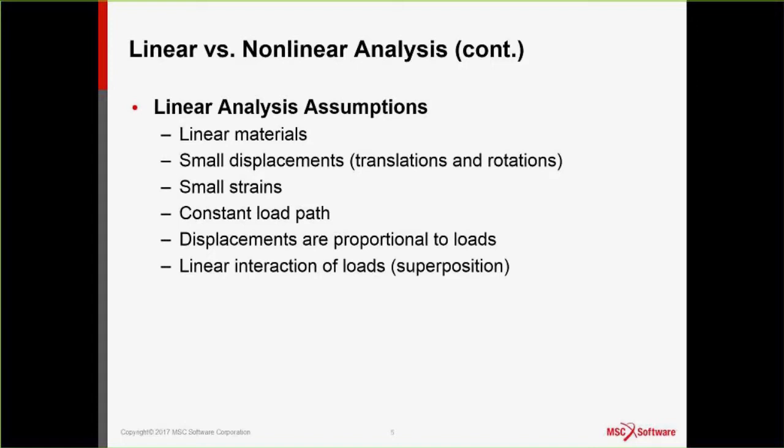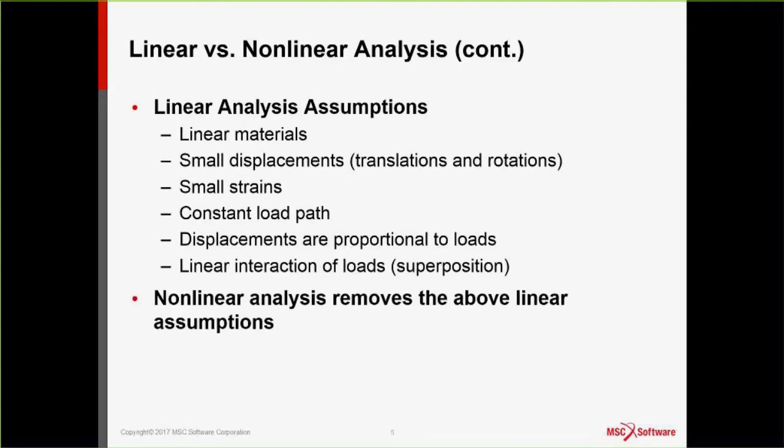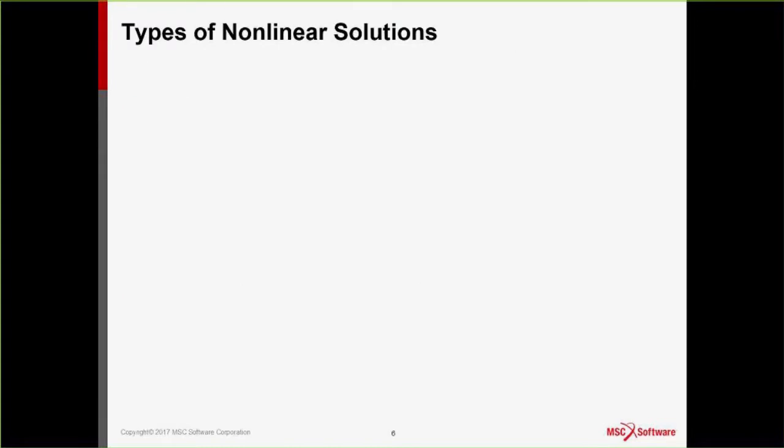And out of it, we can do great things like linear superposition. We can do linear unit loads. We can interact them. We can combine them. But nonlinear analysis becomes important now. For example, if your structure is deforming substantially, going from small displacement to large displacement, maybe rotating quite a bit, then we have to do the equilibrium in the deformed position. Another example would be contact. Once you start having contact, parts touching each other, heel toeing, your load path is actually changing as you apply load to the structure. So those are some of the examples where your linear assumption no longer holds, and we're going to march into nonlinear analysis. So let's look at how we approach nonlinear solutions.